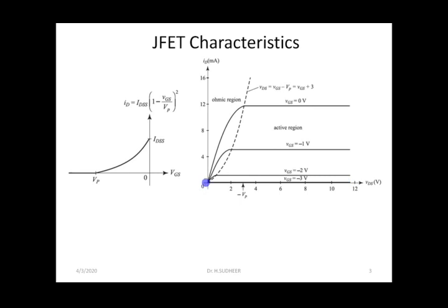So when VGS is equal to 0, like the previous drain current characteristics, as VDS increases, ID keeps on increasing until VDS is equal to minus VP. Once the VDS reaches the pinch-off voltage, ID gets saturated, and we will ensure that our VDS is not greater than the breakdown voltage of VDS.